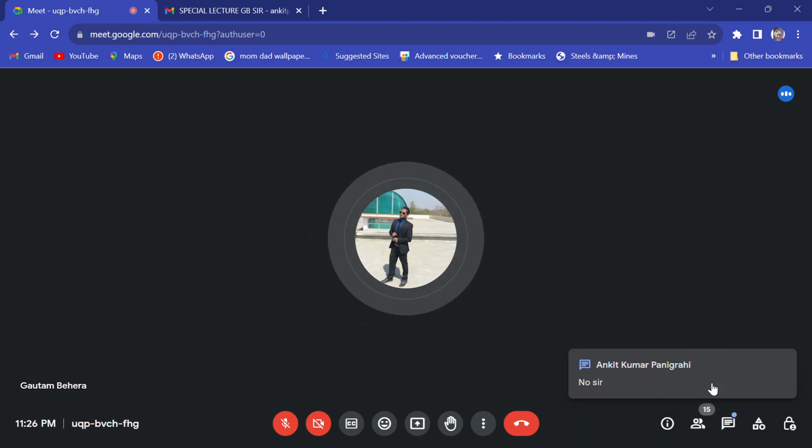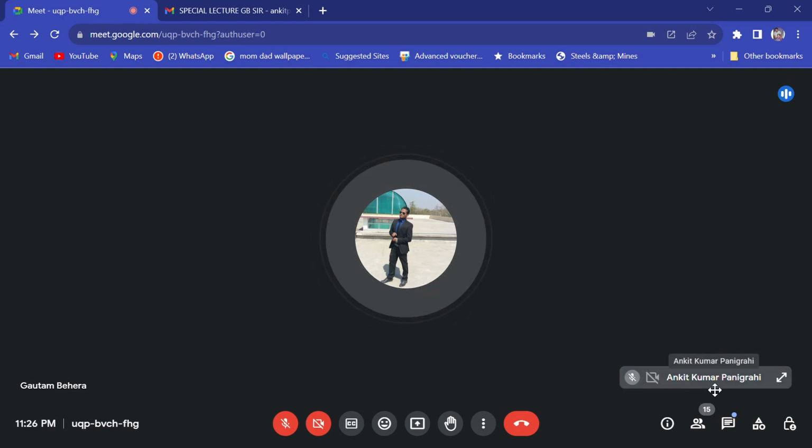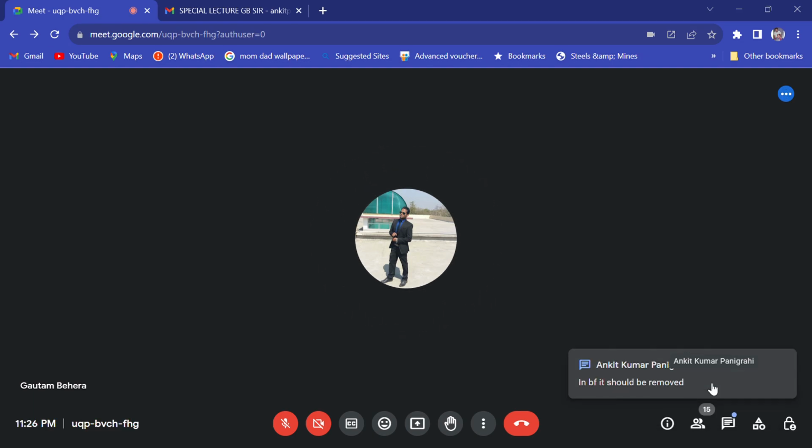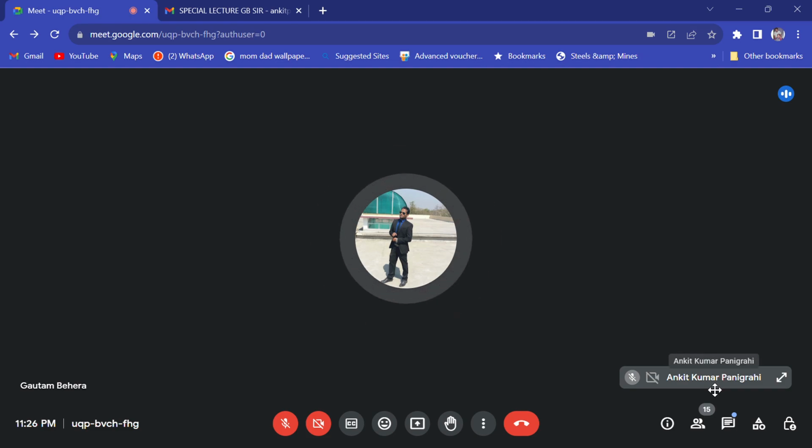You cannot remove sulfur by using an LD furnace. Why? Because the atmosphere is highly oxidizing in nature. To remove sulfur, you need a reducing atmosphere, right? Why is LD slag highly oxidizing? Because it contains a lot of FeO. The weight percentage of FeO is high, right? That is why it is oxidizing. But you need a reducing slag.